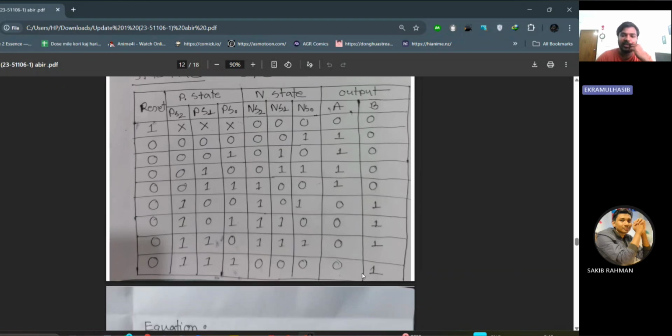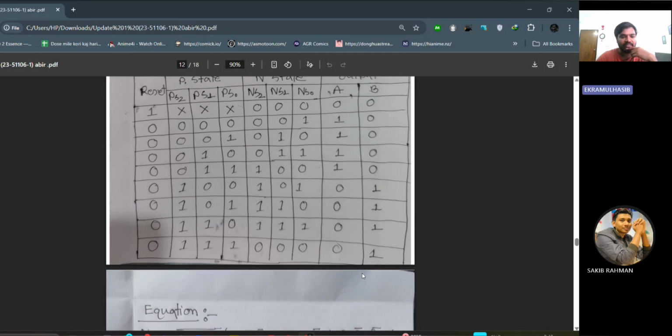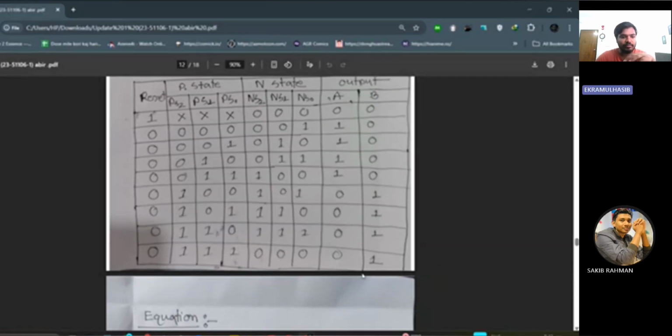So explain this table, and the FSM to clearly define state table where A is active for duration of TH equals to 4 millisecond, and state B where output B is active for TL equals to 4 millisecond. I created a state diagram to visually represent the state and transition, and state table that defines the current state, the next state, output A or B, and counter values required for the state transition.